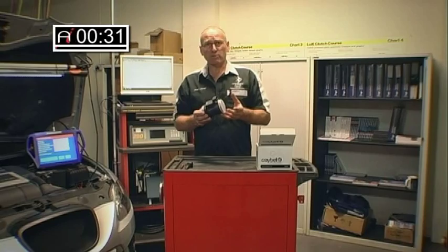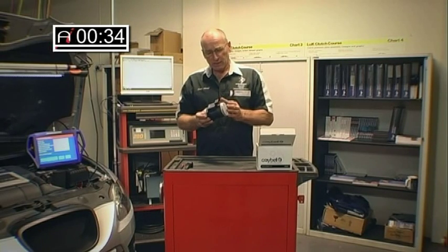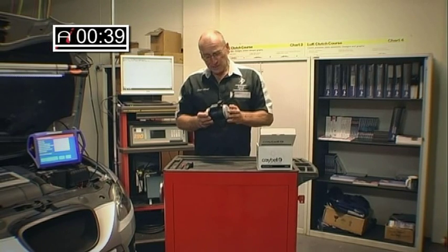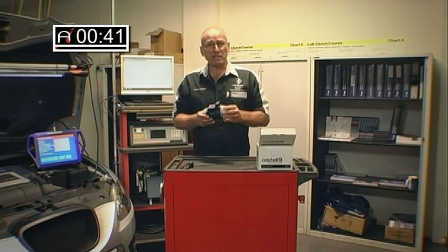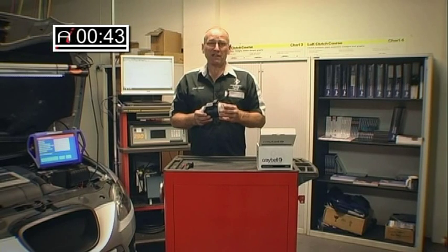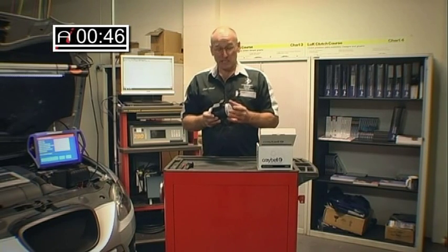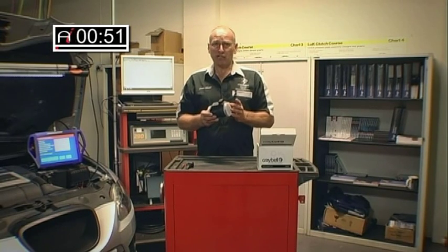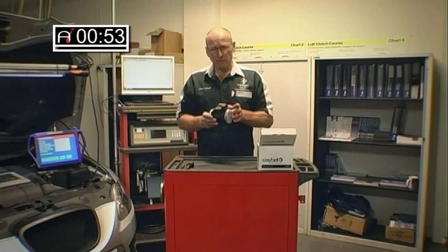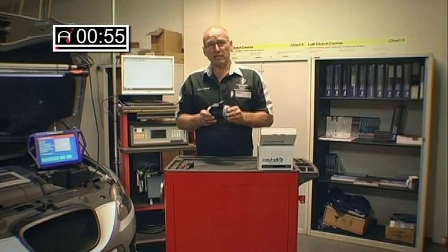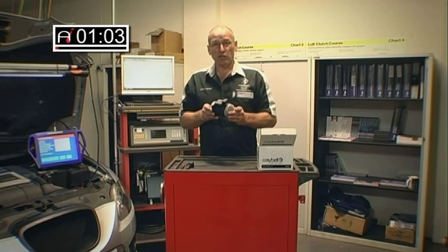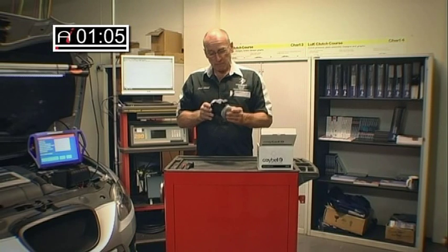Essentially, the engine management computer looks at request. Request is the driver requirement from the vehicle. It then has to compare the request with specified values. Specified values, in effect, are the parameters built within the software in the ECU. And in order to compare those specified values, it has to look then at actual input values. So one of the prime load input value components is the air mass meter. The other obvious one, of course, is the APP, accelerator pedal position or throttle position indicator.